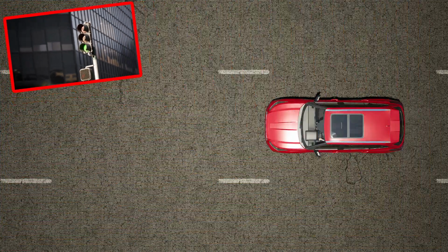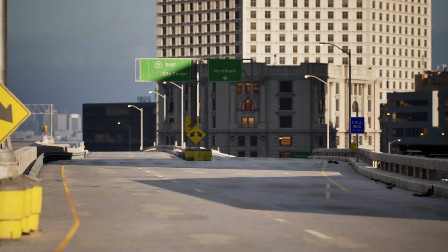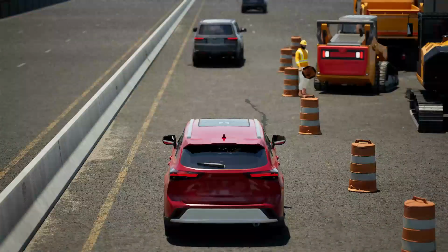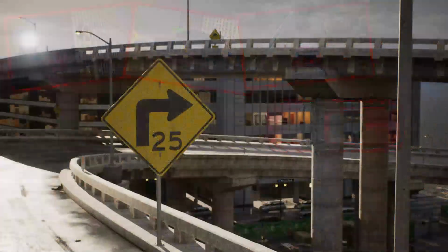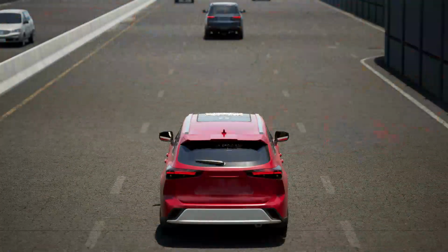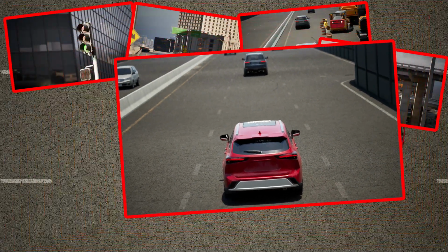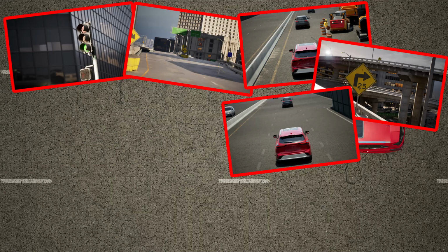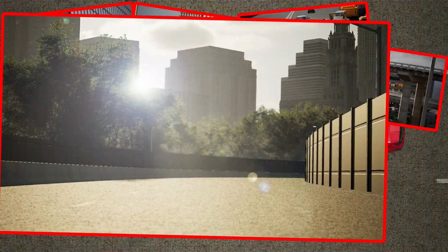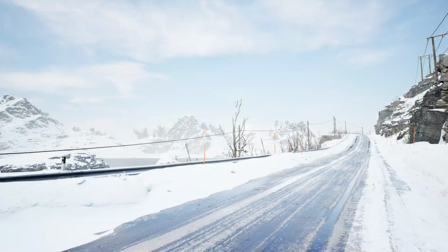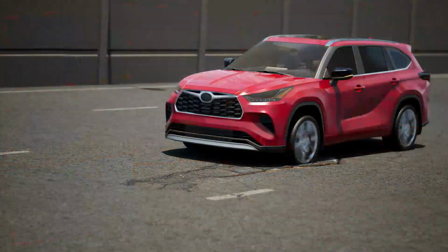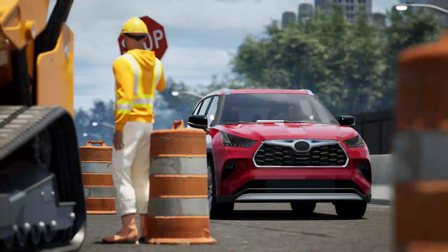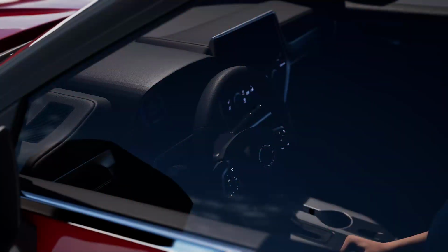It will not operate reliably when there are gaps in lane markings, such as freeway exits and entrances, in construction zones, on sharp curves, if the lane markings and paint are faded. Active driving assistance may not operate reliably at night or in certain weather conditions that impact the ability to read the lane markings. It cannot navigate around potholes, will not detect pedestrians, and will not change lanes automatically.